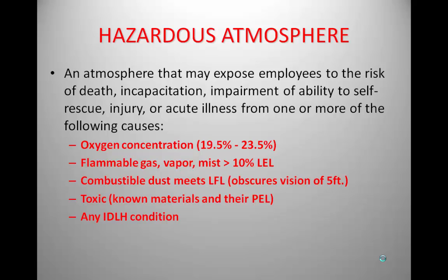On the LEL sensor, obviously you're in an explosive atmosphere. Hopefully we don't get into that kind of atmosphere. Hopefully if we're in an environment, it's going to go off pre that level, before it gets to the lower explosive limit. So at 10%, our monitors are designed to go off at 10% of LEL.